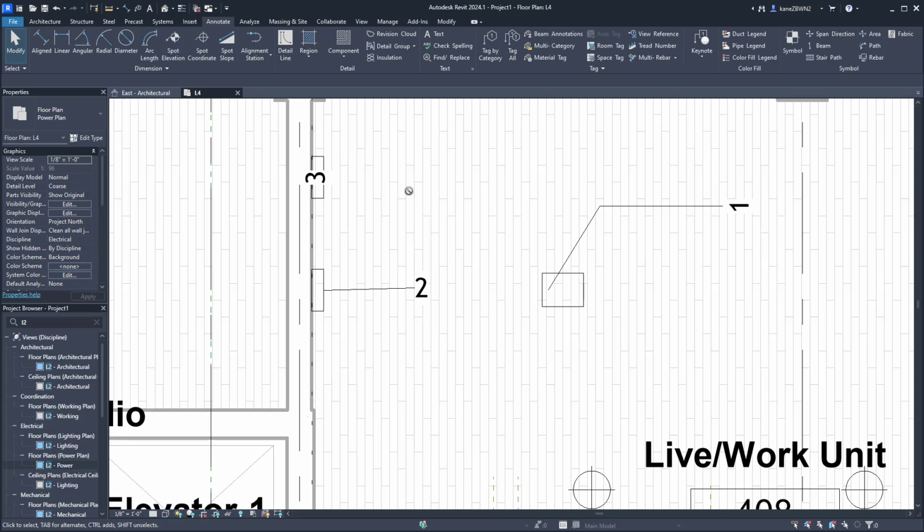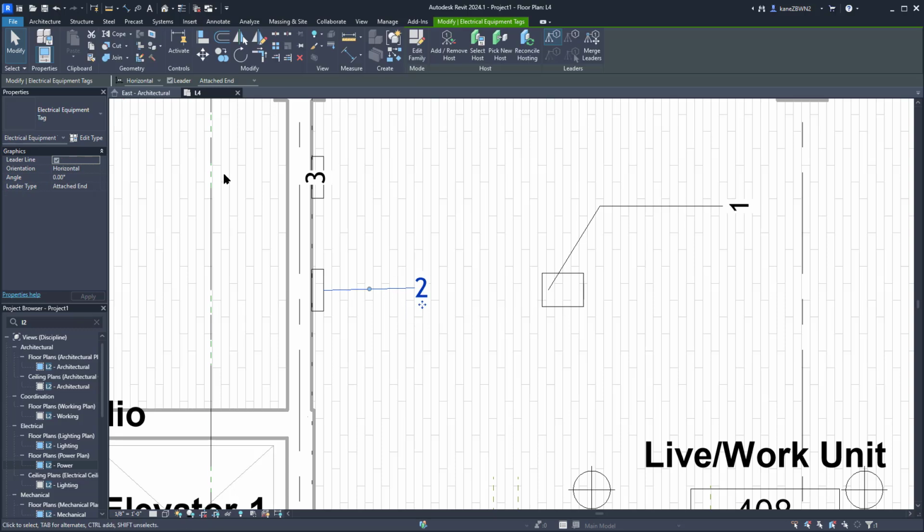You can make changes to inserted tags the same way as most other Revit entities. Just select it and make your changes using the Modify ribbon or the Properties palette. Something else to note, if the tag displays the value for an instance parameter, such as mark, you can double-click the tag and change the value for that parameter without having to go find it in Properties.